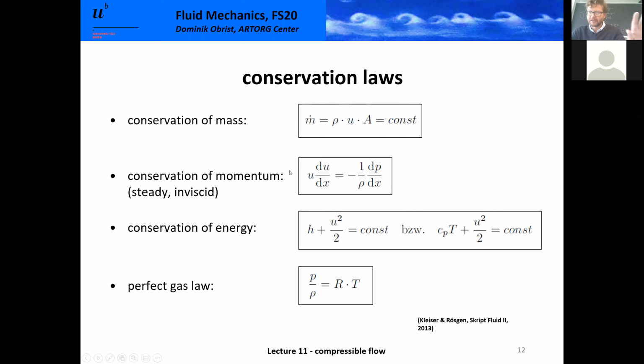That one drops out because we're studying only steady flows. We're not considering changes in time. So what remains is the nonlinear term, u du dx. That's the only term that remains because we're only looking at one-dimensional flows. We don't have the v and the w. Okay, so u du dx. This side here looks almost the same as Navier-Stokes with a few terms kicked out.